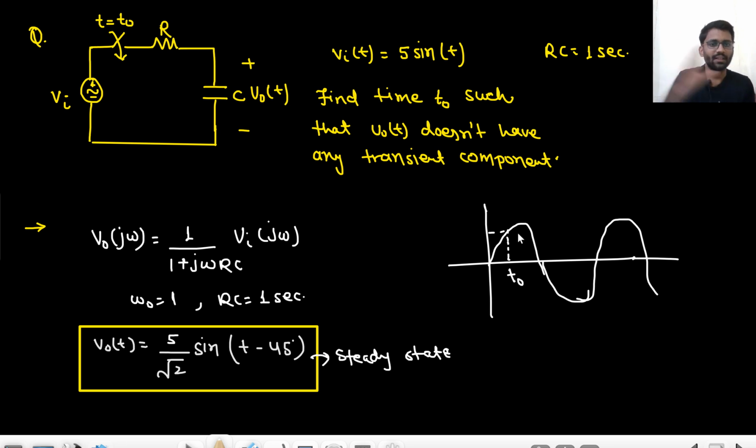My RC circuit would see there is a sinusoid input. Based on that, it will give me a response. The response that it gives me is like this. Then I got to know at t equals 0, my steady state response is giving me minus 2.5 voltage. But at output, I am expecting 0 voltage. So that's why I need to add plus 2.5 transient as well, right?